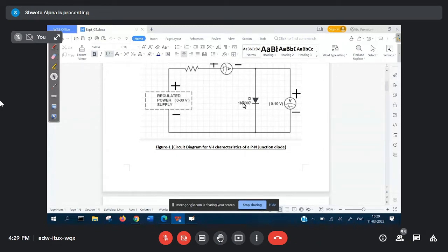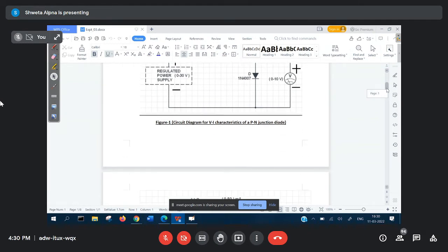So if you have a silicon diode, we keep on increasing 0.1, 0.2, 0.3. Ammeter value is almost zero current. But once the value of input voltage is about 0.7, 0.8, something like that, we will find that ammeter begins to show us current, and the current value after that is increasing sharply. So that will be our knee voltage, and this is how the process is taking place. This is the behavior of the PN junction diode, VI characteristic of diode.